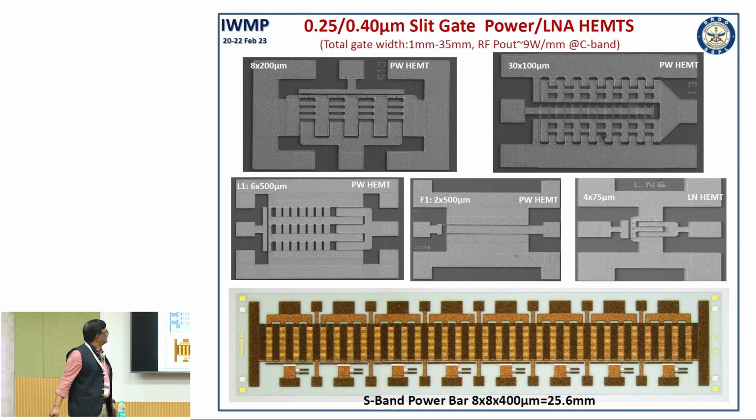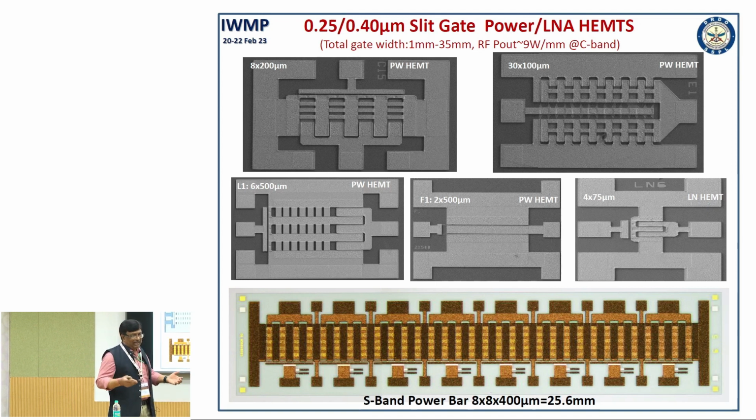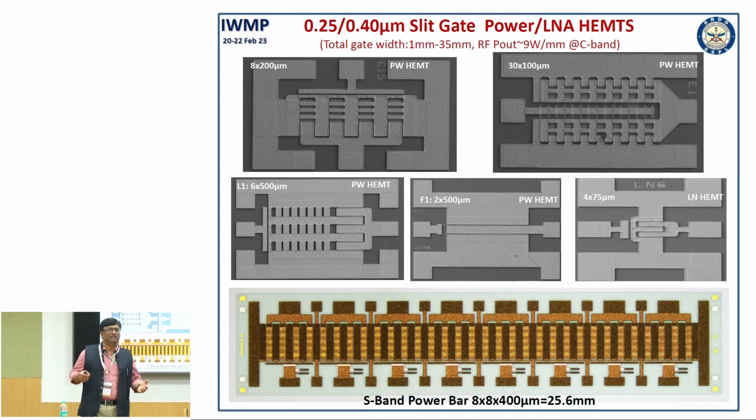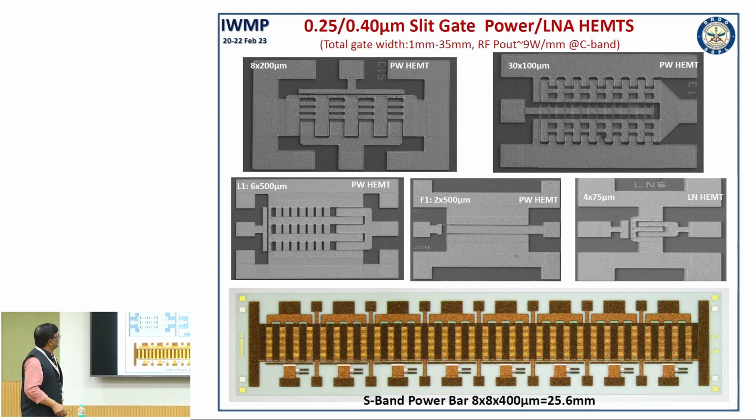18 gigahertz. And these are a few of the devices with multiple gate configurations, and we now also have a 130 watt device with 64 fingers. Again, device complexity comes from the number of gates. Each gate has to be working, otherwise you will not get your device with the desired performance.